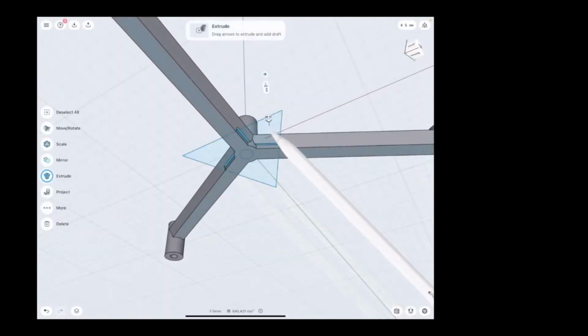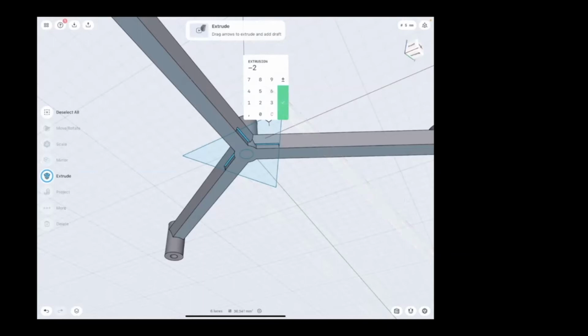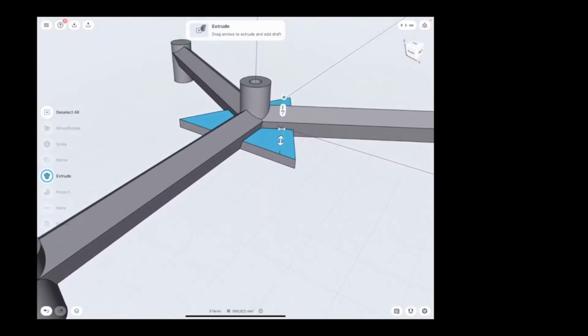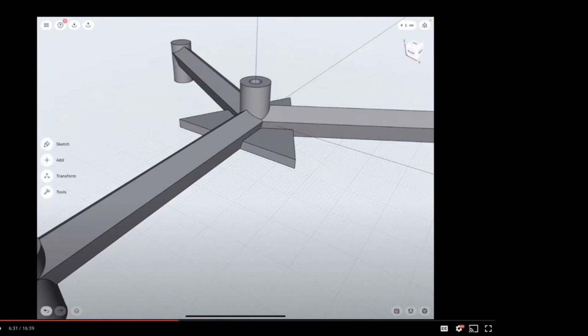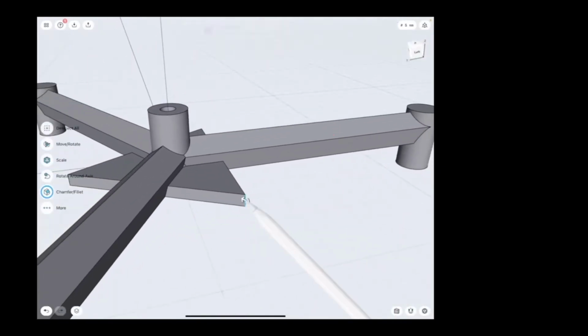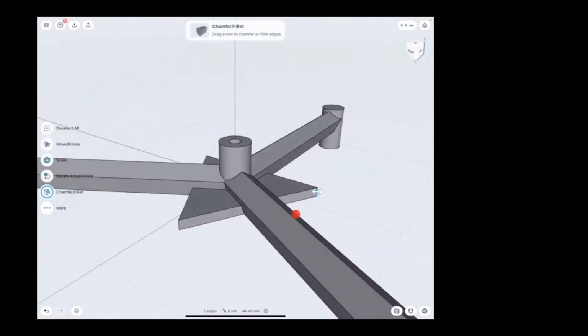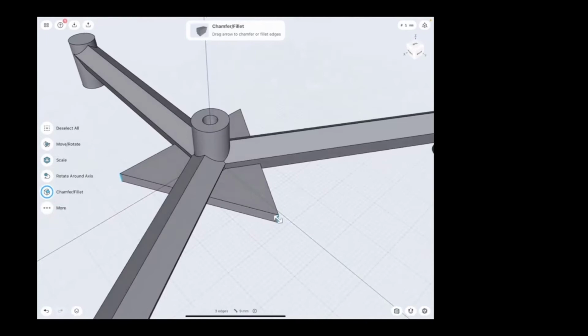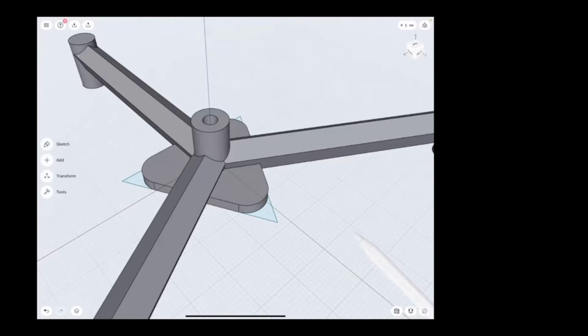And in this case, I'm looking to create a 3 millimeter extrusion that merges together with the channels. So I'm gonna select Union, and I have that flat shape with pretty sharp edges. So let me select these 3 edges and apply some chamfer or more of a fillet on them. A 6 millimeter fillet will be perfectly fine for me now.